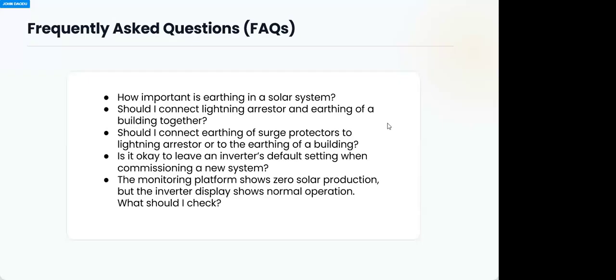such that when it's charging, that bulk voltage will not be exceeded. It is the function of the charger now to say, okay, because you have programmed me not to exceed 27, when I get to 27, I will hold it there until the battery current decays. Then when everything is sorted, depending on the function of the charge controller, it will go back to float.